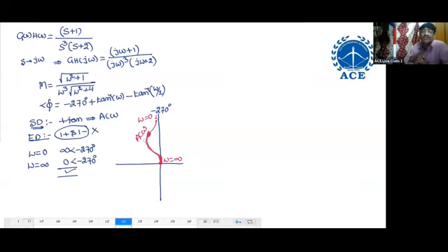If you have any doubts, substitute omega equal to 1 and check the angle. The angle is less negative than minus 270, around minus 250 you will get. Minus 250 means which side? Here, it is not a straight line. So simply, positive tan is large, so the plot is pushed in the anti-clockwise direction. Okay?